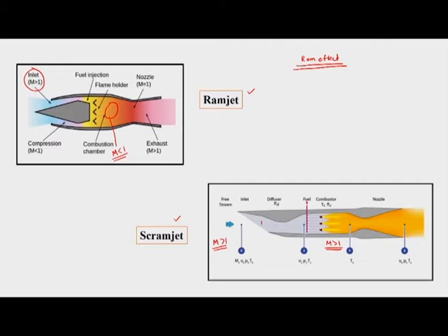So, we have the scramjet engine, and the requirement for the scramjet engine would be to have still supersonic flow existing in the combustion chamber. So, we will define the intake efficiency, which is called ram efficiency. While defining ram efficiency, first we will try to plot the TS diagram, then we can understand what is practically happening in case of an intake.